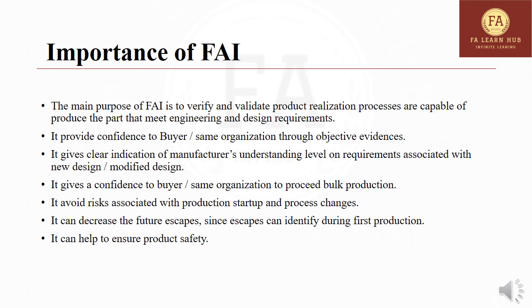The second point: it provides confidence to the buyer or the same organization through objective evidence such as measured values of dimensions, automatic test reports, images if required, etc. It gives a clear indication of the manufacturer's level of understanding of the requirements associated with a new design or a modified design. So by performing FAI, the buyer or designer can understand how correctly and how deeply the manufacturer understood the new requirements.